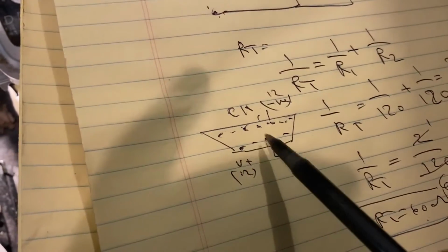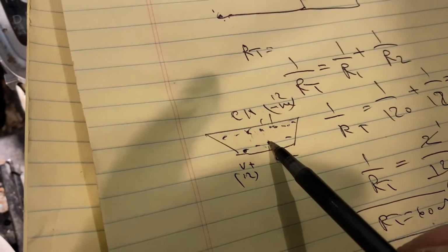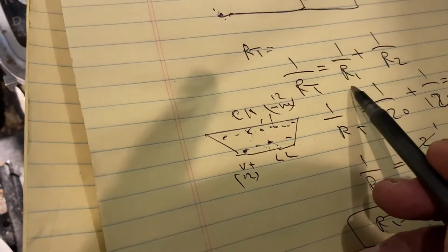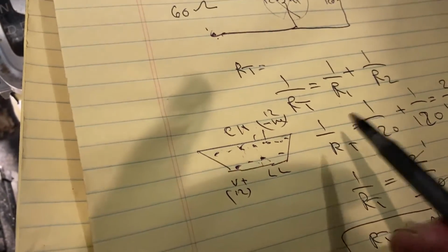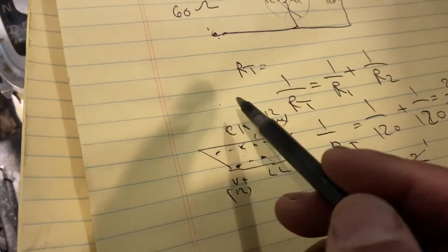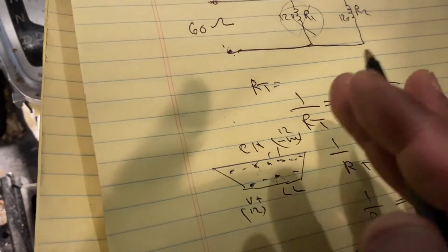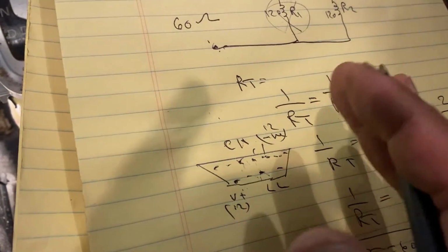I'm going to check first by the OBD, make sure everything to the OBD is good. If you get the 60 ohm, it will be perfect. We're going to go ahead and see what the last work being done was, either in the airbag module or the ABS. So we don't touch the ABS, because you have to start from one point. You have to see what is the history.